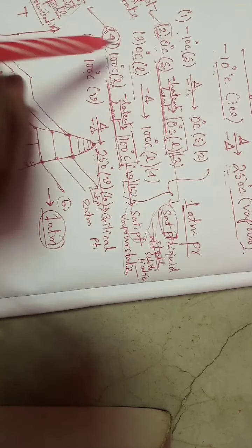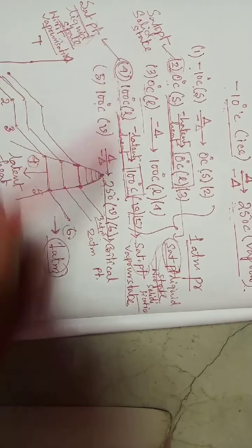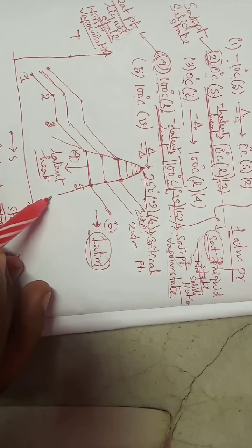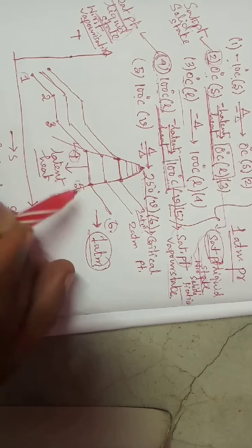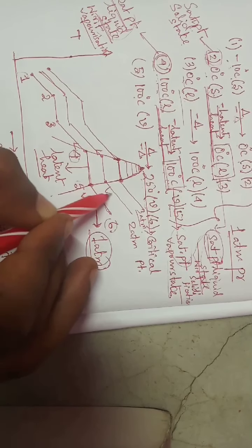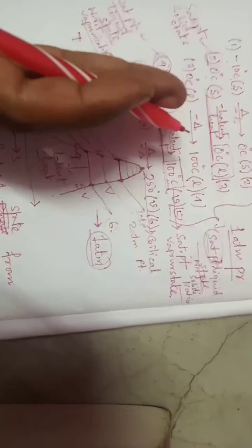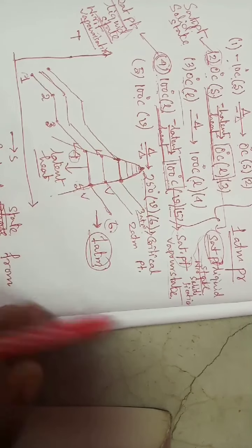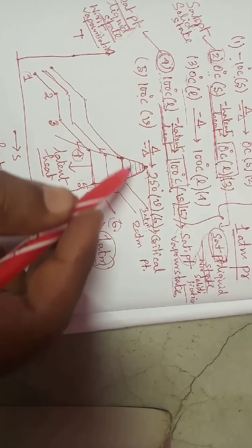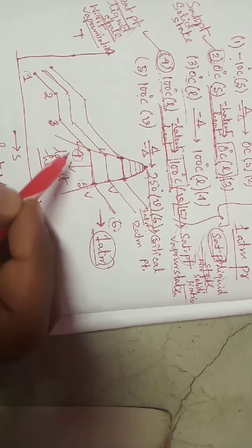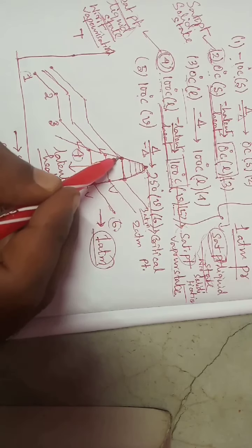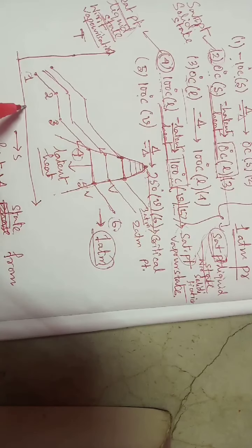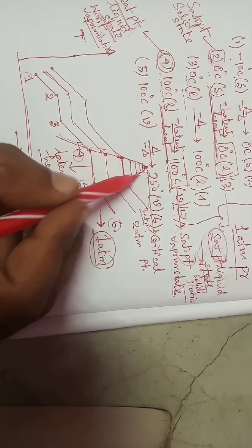Okay. So we are getting 4 saturated points. Now this is our concerned area. Why is this our concerned area? This is the liquid portion, this is the vapor portion, this is the liquid portion, this is the vapor portion. Means left of this line is liquid portion, and right of this line is vapor portion. Because in a thermal power plant we have water and steam condition. That's why this liquid and vapor portion is very much important. That's why in the TS diagram we are representing the Rankine cycle in this region.